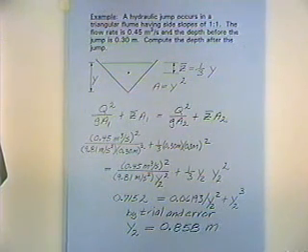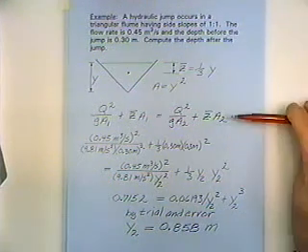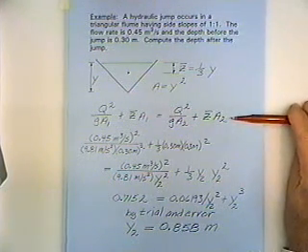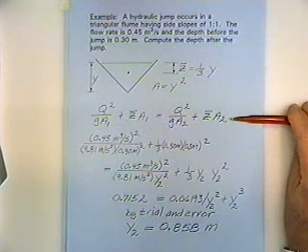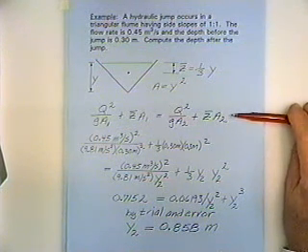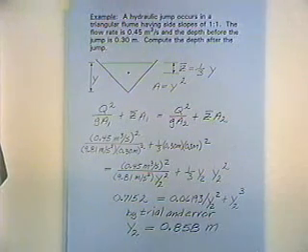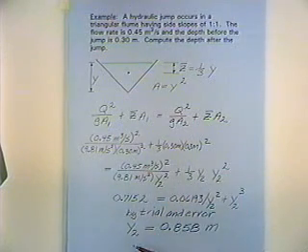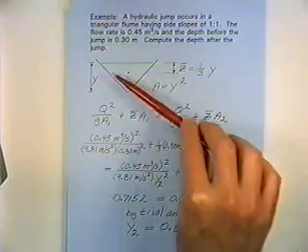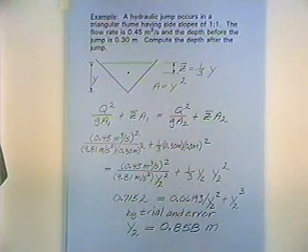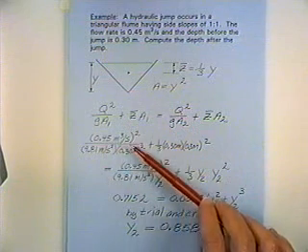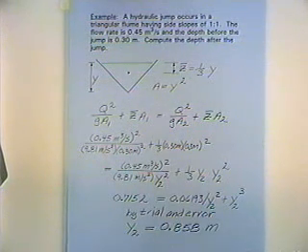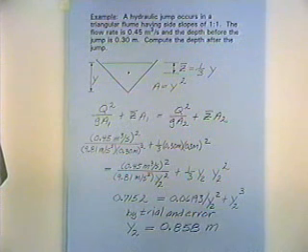It's a problem of just plugging the numbers into the equation. There's a specific momentum equation, which I'll let you go through the derivation of at your convenience on the previous page of notes. That's the basic equation, and here we're plugging in the numbers. We know the depth before the jump, and we want to compute the depth after the jump. Just knowing the geometry, we can plug in the numbers. The flow rate is 0.45 cubic meters per second, the same upstream and downstream. The acceleration of gravity is a constant, so we can plug that in.